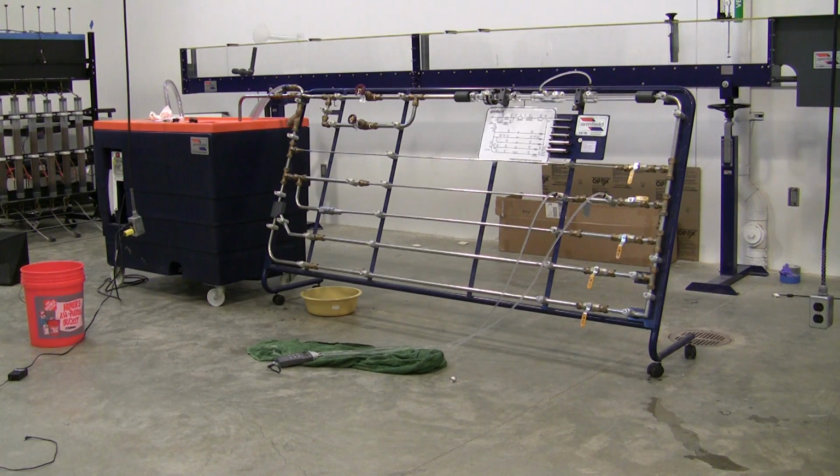That's the conclusion of this lab experiment. Just to recap what we've done, by measuring the pressure difference through a fitting, we're able to use the local loss equation, which says the head loss is a function of K times the velocity head. Since we'll know the velocity, and we've just measured a pressure difference, which can be used to calculate the head loss, then the unknown in that expression will be the K value.